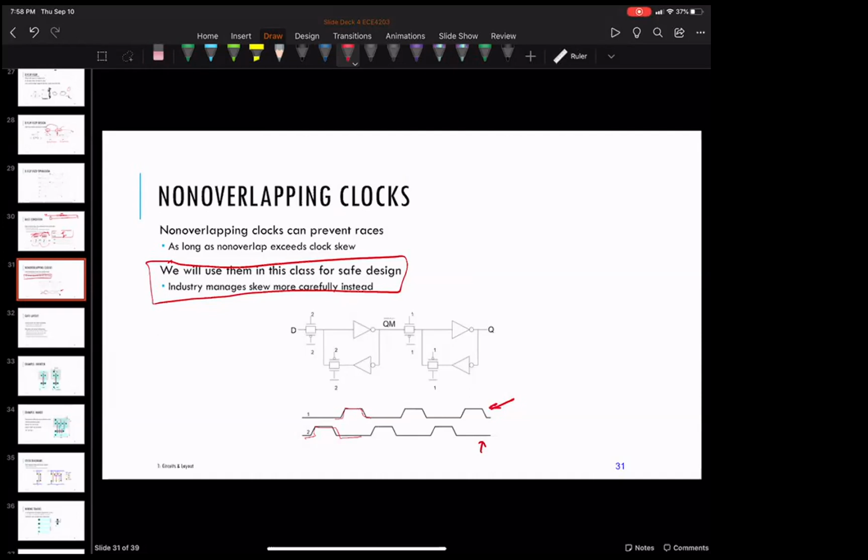We have some other kinds of circuits, but this is sort of 99% of your circuits: combinational circuits made from static CMOS logic and transmission gates, and then sequential circuits made from latches and flip-flops. Okay, and then we'll look at some of that extra 1% later.